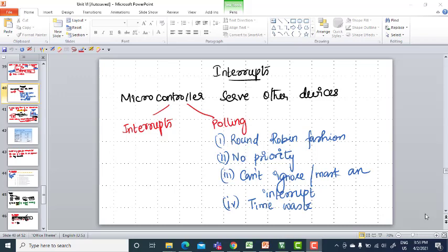In the main program, let us transmit a character serially. We are doing it in port 1. Let us transmit the character V repetitively. So port 1 is going to transmit the character V, and P1.0 is going to generate the square waveform continuously. These two operations can be done parallelly if we use timer interrupts.